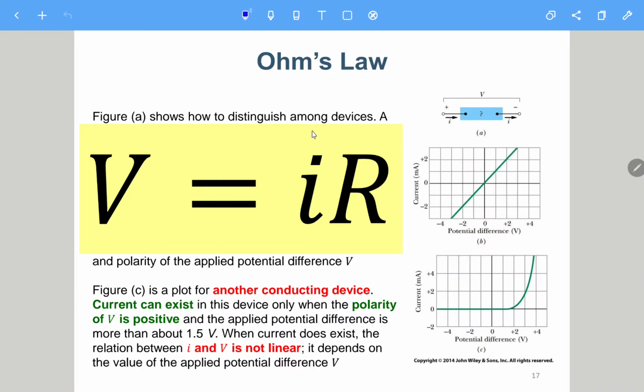So here we are talking about Ohm's law. I don't think it will be difficult. We just need to remember that Ohm's law is V equals IR. This is a resistor, the current going through is I, and V is the potential difference across this resistance. That's enough. Actually, this Ohm's law holds for some electrical devices, but for other devices it might not be like this. This is the so-called linear case: it is just a straight line, with current on this axis and voltage on this axis. The current versus voltage is a straight line, but some other elements are not like that.